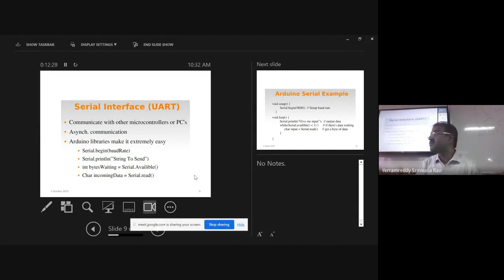Okay. There is no keyboard and display, right? Even if the keyboard is there, how will you enter the data? You cannot jump and enter the data. So it has to be wireless. Understood? So that's why, please remember, in a computer, stdio.h means only ASCII keyboard and monitor. However, other than a computer, there is no guarantee what stdio.h is, because we don't use such a big keyboard and display in all our products.